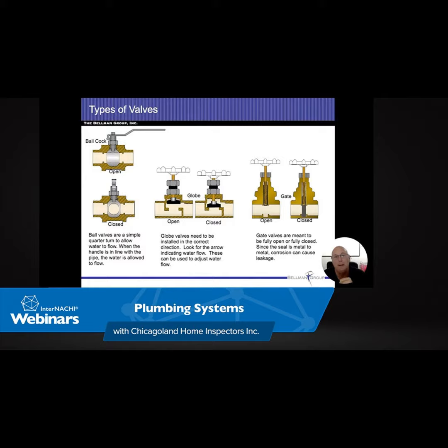And we run into this with heating, with venting, and also with our plumbing waste lines. So the drainage, 1/4 inch per foot down. Our vents, 1/4 inch per foot up where it comes to it. So we want the warm sewer gases to go up, and we want the wastewaters to go down.